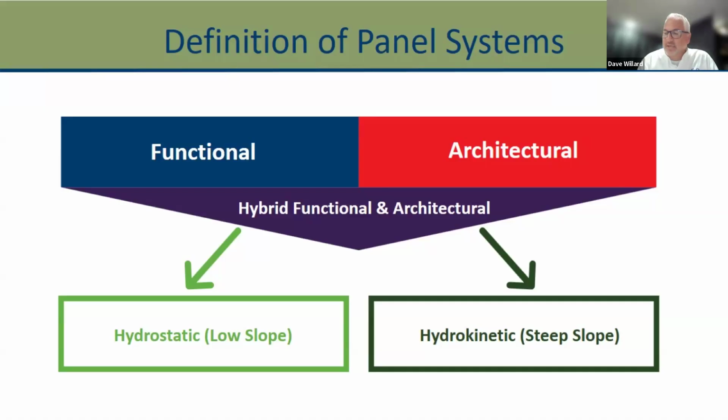And typically we talk about low slope being about 1/2 to 2 inches, 2 on 12, to steep slope being 2 on 12 or greater. I know low slope they also will consider 1/4, but with the way things settle, I think once you start getting down to 1/4 on 12, that's pretty much a flat roof. So, but steep slope is typically 2 on 12 or greater.